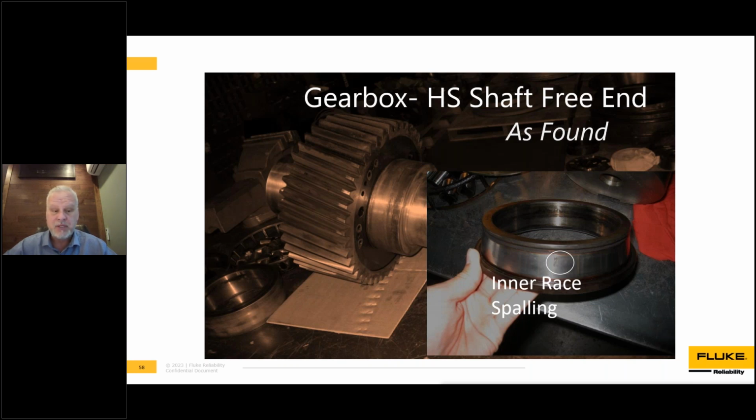And as I mentioned at the beginning, when we have slow speed machines, we have found at least 30% of the time the impacting is the only indication we ever get. If we get to failure and we go and look at the data afterward, impacting is often trending early and we never see any changes in the regular data. So we have become much more dependent on our impact tool, as well as thoughtful and attentive to the data that comes from it.